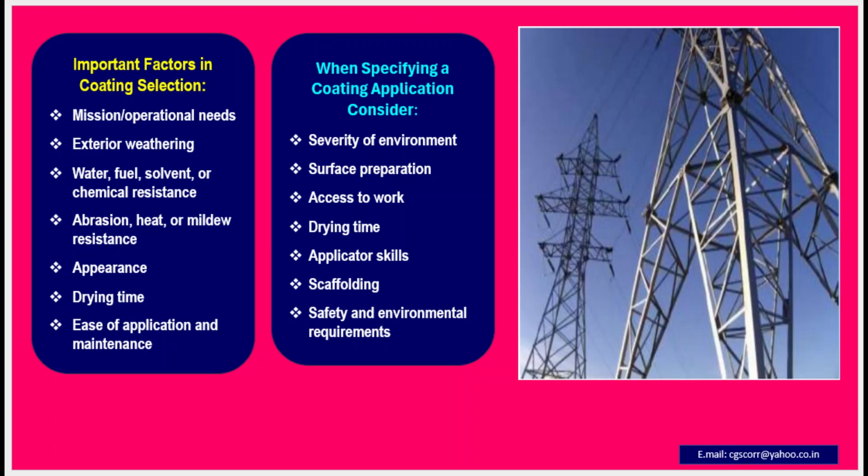The foremost important factors in coating selection are mission, operational needs, exterior weathering, water, fuel, solvent or chemical resistance, abrasion resistance, heat resistance and mildew resistance, appearance, drying time, ease of application and maintenance.